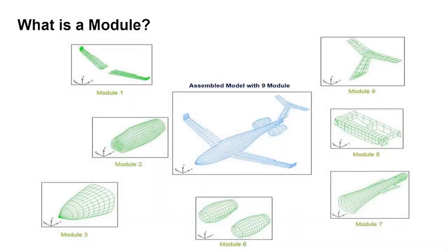So next I'm going to be talking about modules. So what is a module? This is a useful feature that has been added, and it has multiple applications in several industries such as auto and aero. So today's industry requirements call for design of complex structures, as I said, again, a similar concept, that have multiple components, parts, and assemblies, and combining these parts and assemblies can be tedious and cumbersome at times. So modules are similar to part superelements, however, they don't have any reduction, so that's the benefit. It gives you more capabilities, so you have more control using the module.